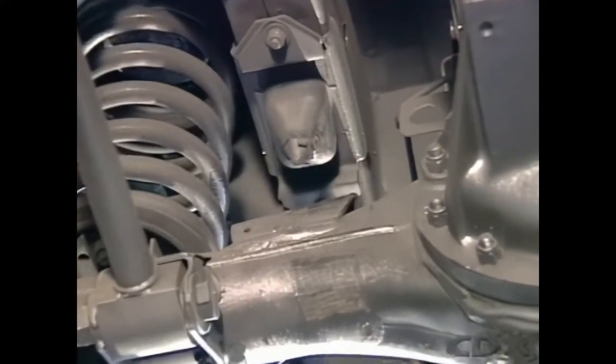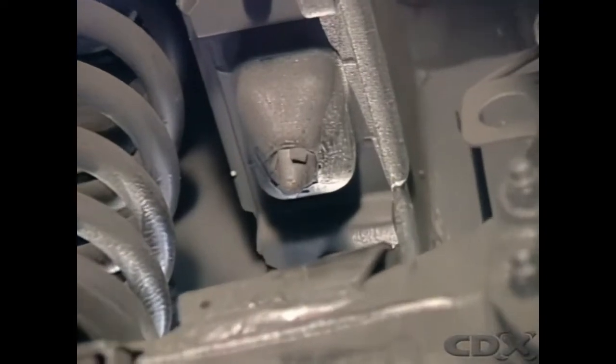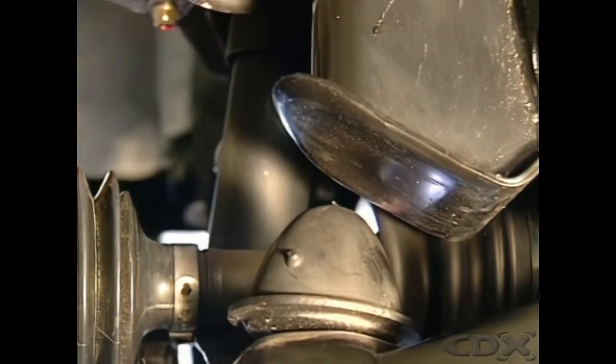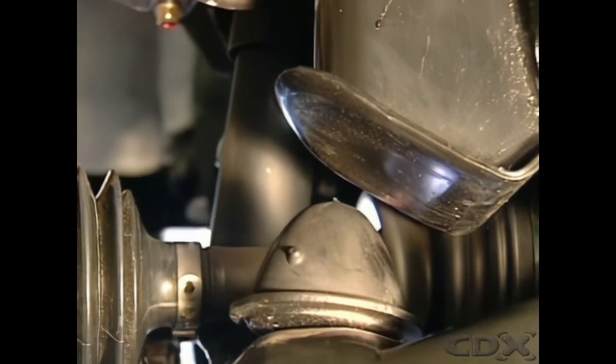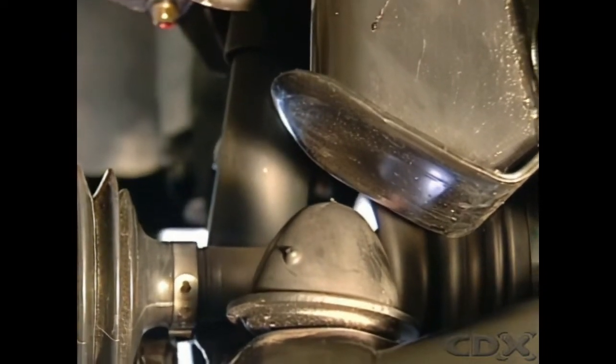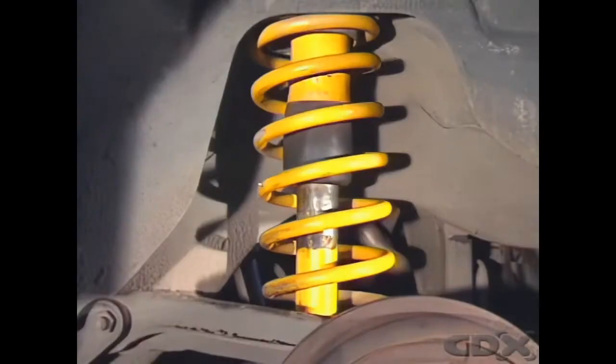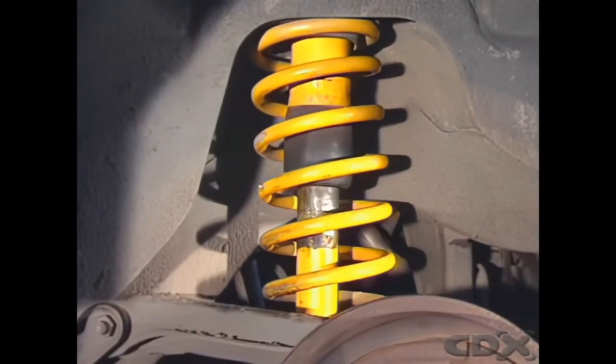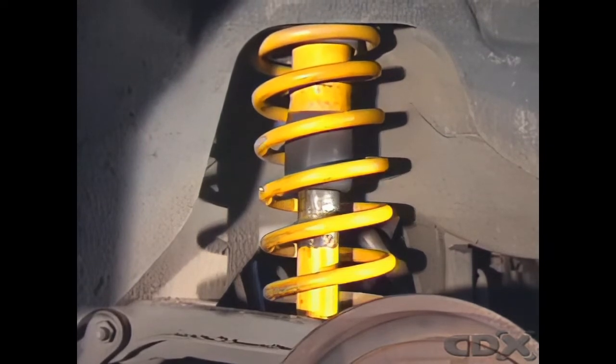Non-metallic materials like rubber can provide the main springing action, but are more commonly used as stops to limit extreme suspension movement. The stops can also be shaped to provide an auxiliary springing function. In light vehicle applications, air is normally used only for ride height control.